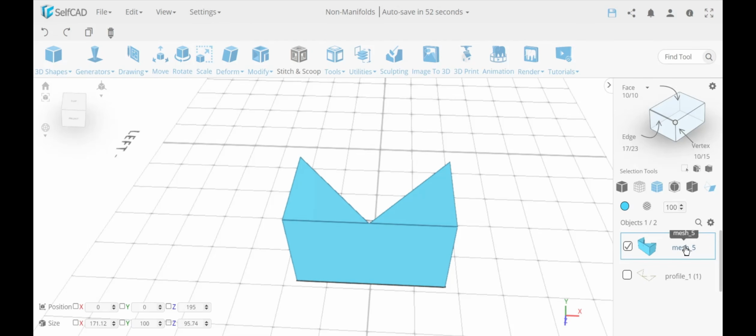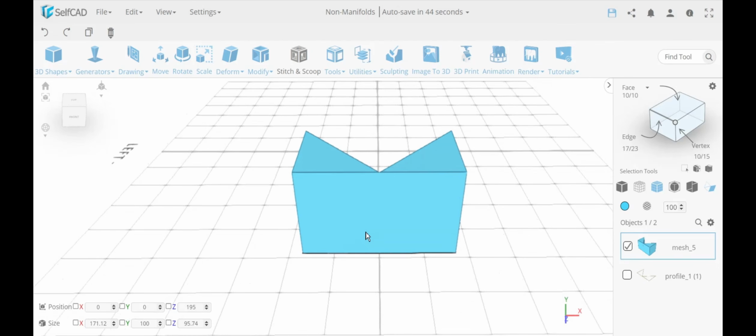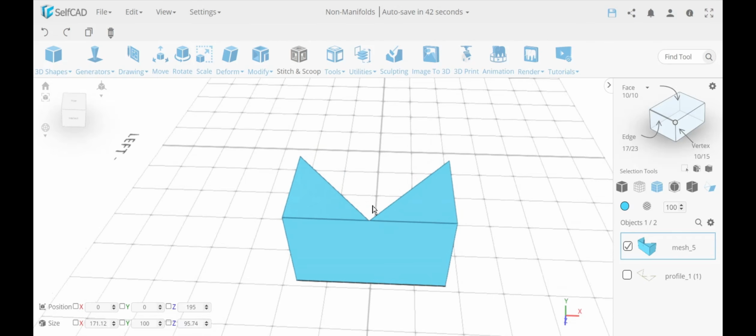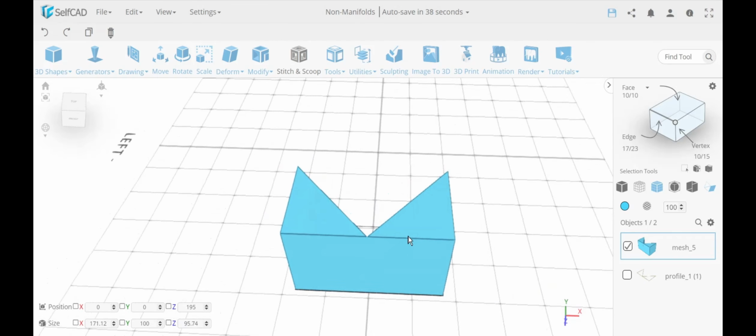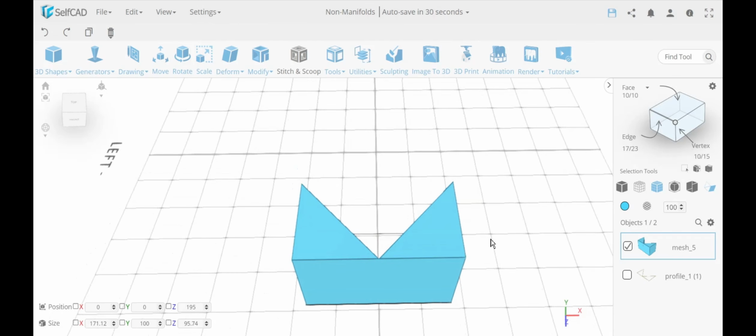as a single object, combined, merged, or grouped together, there will be no problem, as I said before in the previous examples. But if they are combined together, in this case they're joined, like the back face, or joining them, and also merged vertices, they're completely joined together, then they must have a volume connection. In this case, there's no volume. If you put in, for example, water on this side, it will not be able to go over to the other side because it's choked over here. There's no volume going over.